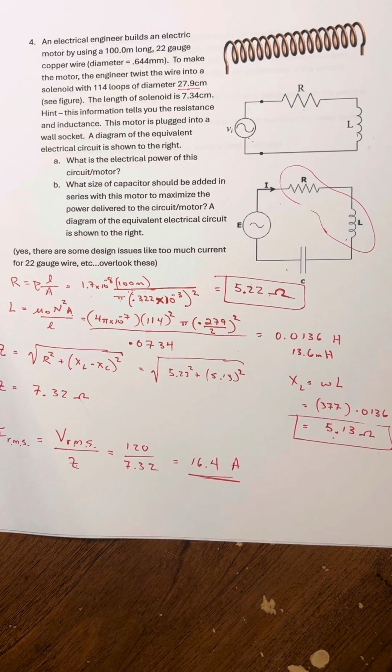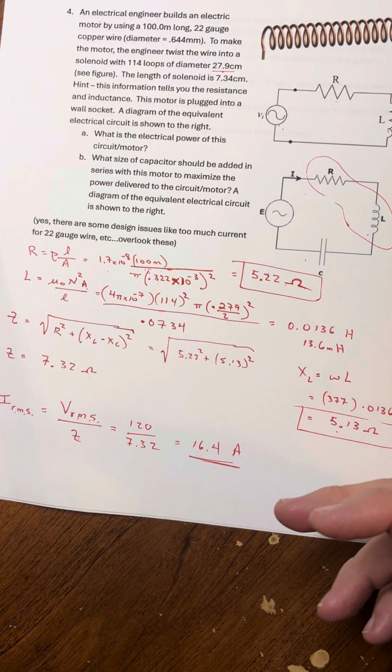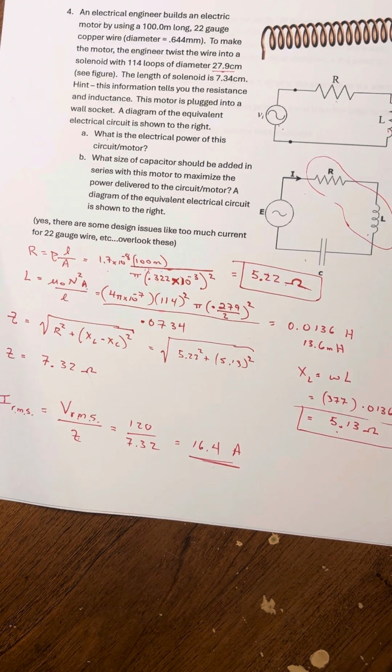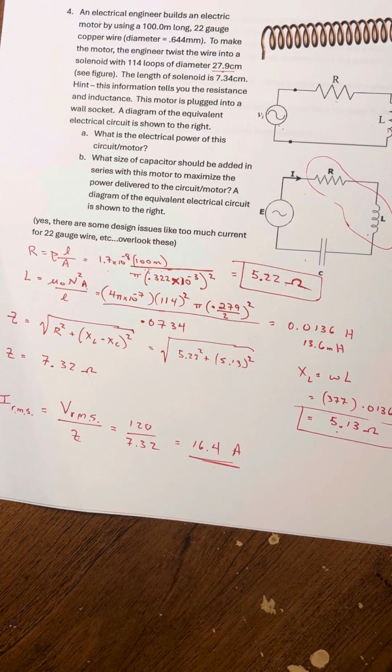So it'll be a little bit more than many of your plugs. Depending on the age of your house, they can be 15 amps, but a lot of them can be the higher 20. This could be in your garage, your bathroom, your kitchen. They usually have a 20 amp one there. Outside, it probably depends on the age of your home. My home, sadly, has a 15 on the outside, and my compressor needs about 16. It's really obnoxious. But I plug it in the garage.